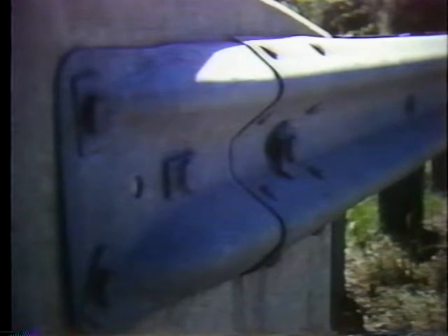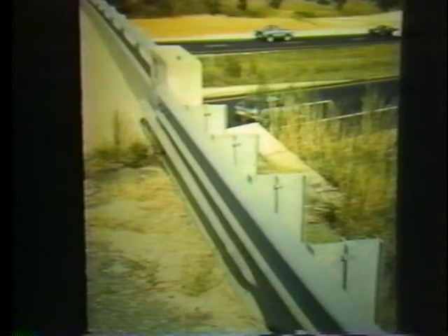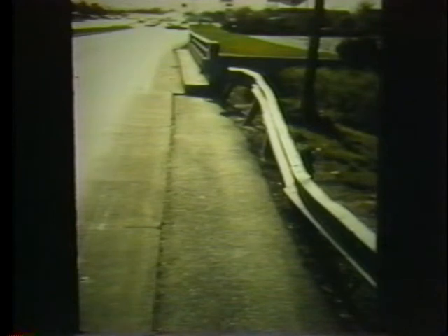In this well-installed transition, the transition stiffening and blockouts are obvious. And this is a poor structural connection because, as you can see, the installation doesn't have all the bolts called for on the end shoe. Here is an obvious field fix. This is an untested transition with visible potential for snagging. And here is a good use of a rub rail in a transition. In this last picture, you can see obvious pocketing problems in this poor transition.